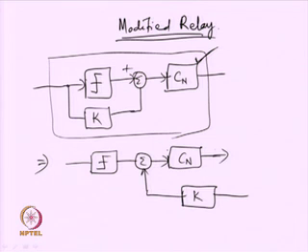So, please keep in mind. So, when I have got my Q1 here, okay, because the loop interactions have gone, with the proper choice of Cn, it is possible to eliminate the loop interactions, and the TITO system can equivalently be represented by a transfer matrix which has got only diagonal elements Q1 and Q2.